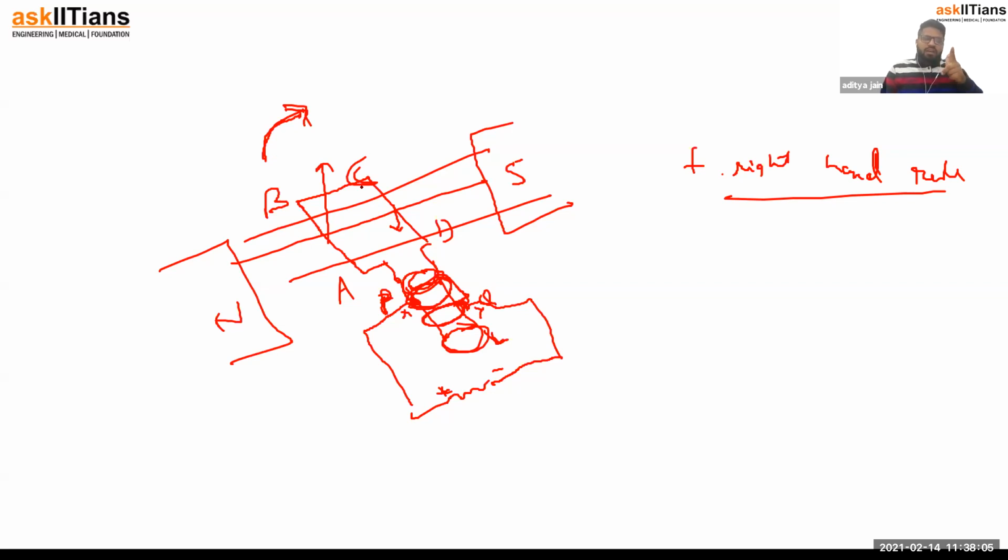What is the direction of the magnetic field? It is given by the forefinger. And you see the direction of the magnetic field is north to south. So the situation is like this. Thumb is pointing upward, that is the motion of the conductor. This is the magnetic field, forefinger. So the middle finger will give the direction of current, that is coming towards you or from A to B. According to the figure, the direction of induced current is from A to B.